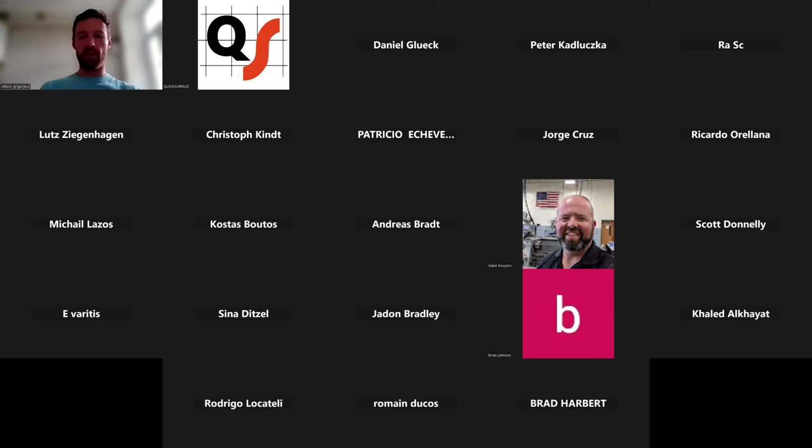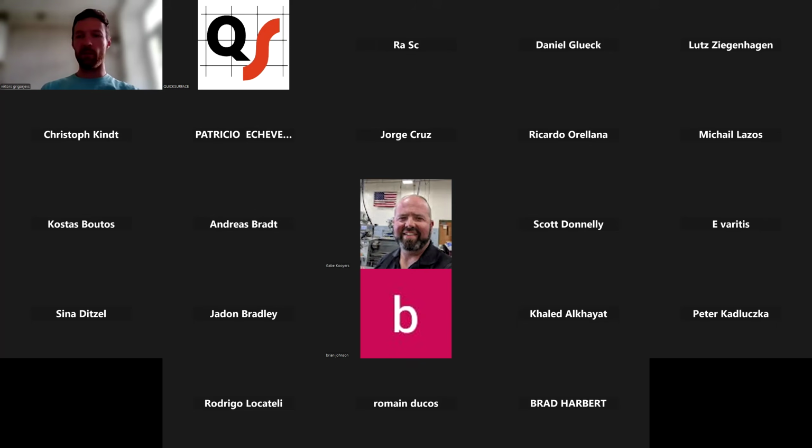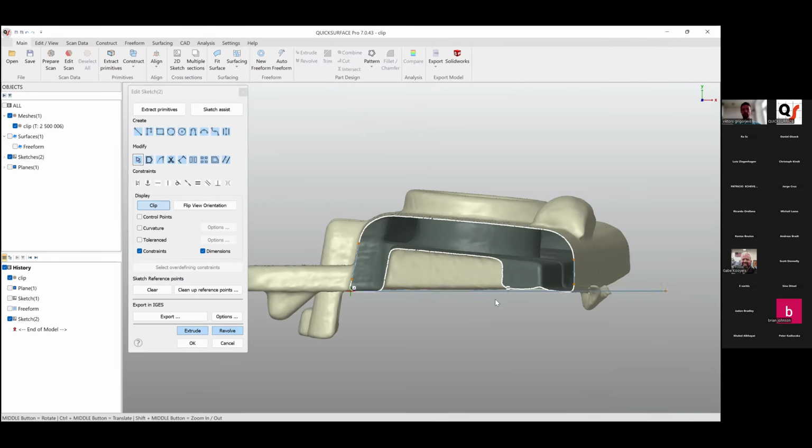Basically, extrusion is typically normal to our sketch plane. So that means it will go completely vertically, and even if we are using draft, we won't match these surfaces. So to fix this problem, I have created these two lines that represent the angle of these surfaces.